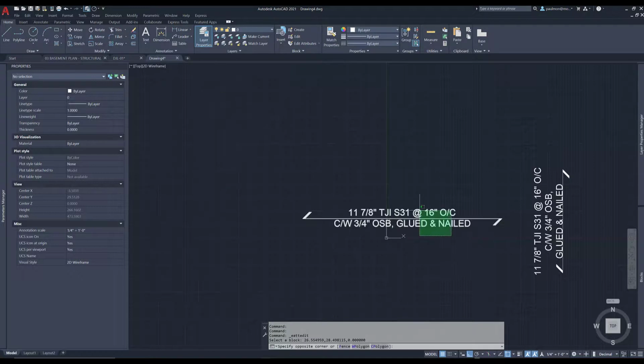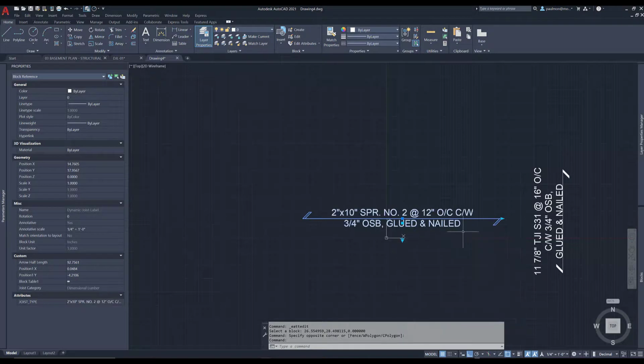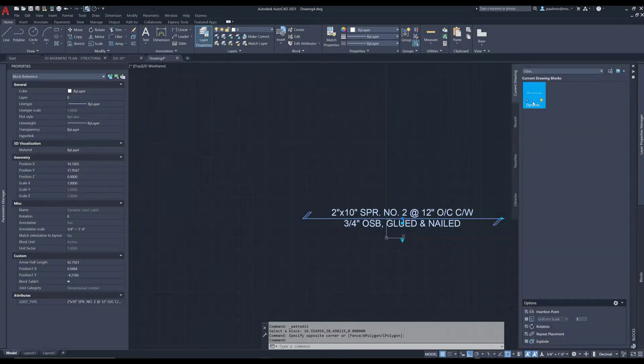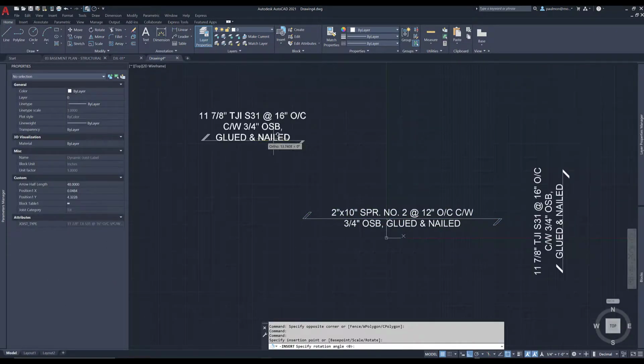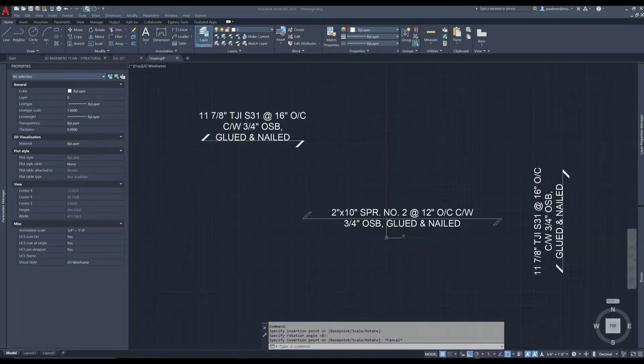Now if we change it to dimensional number, see if the graphic will update, and the graphic did update. The fill in the arrowhead is turned off, so this is how it's supposed to behave. So this is working properly. Now if we want to insert another one, if we go to the block tab here and then click in here, and then we can just place another one. Now because these entities inside the block are on layer 0, it should take on the color and linetype setting of the layer definition. So let's test this out, make sure that it's working properly.